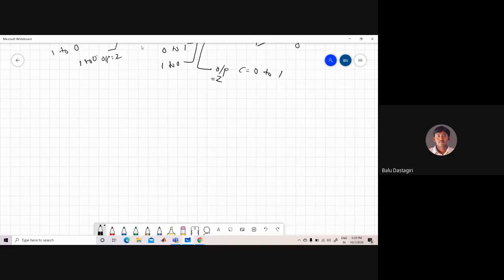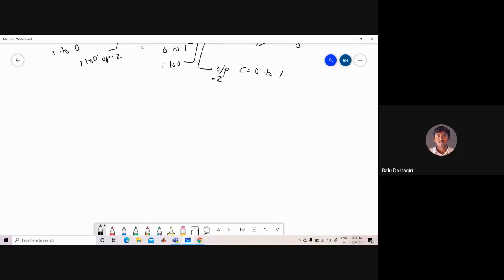For example, there are some more delays you can specify here. If you are taking the bufif1 here, bufif1 hash, you can specify like this: bufif1 #(1:2:3, 2:3:4, 3:4:5) G3 (Y, I, C). So it is one type of delay we can specify in Verilog.